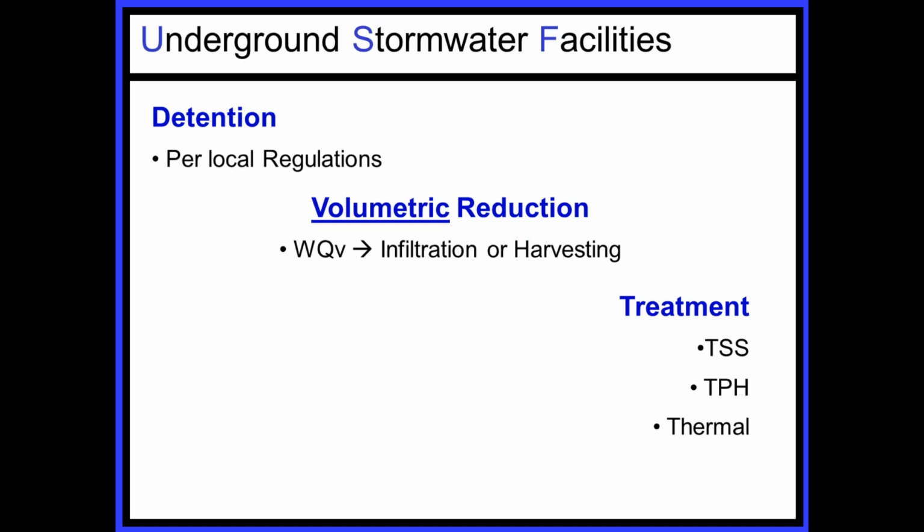And finally, treatment. You see a pervious pavement that's clogged, and the reason why it's clogged is because you have an upstream drainage area that's dirty, that's draining to that area. So how do we pre-treat? How do we ensure that the best management practices are sustainable long-term? And the way you do that is through ensuring you have pre-treatment methods in place in order to accomplish that end.